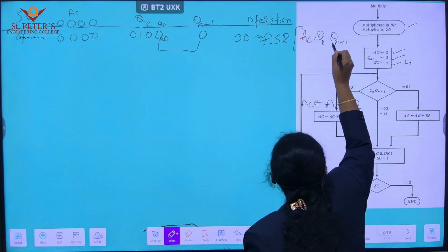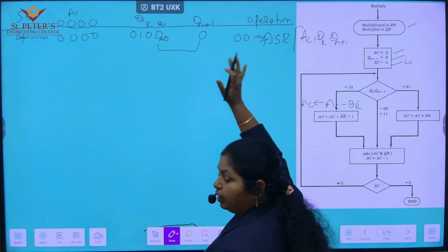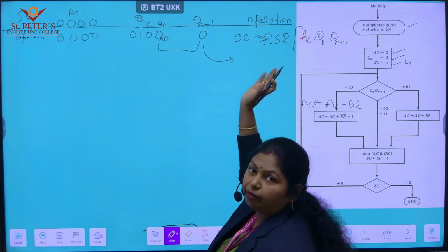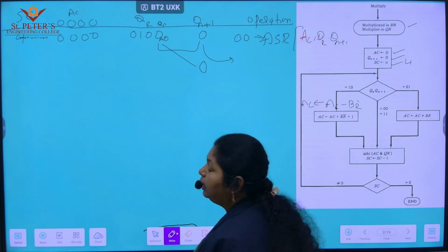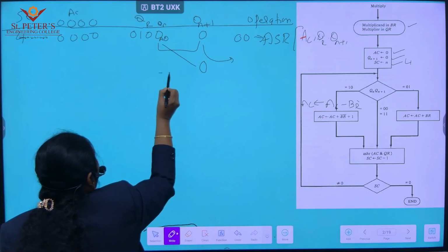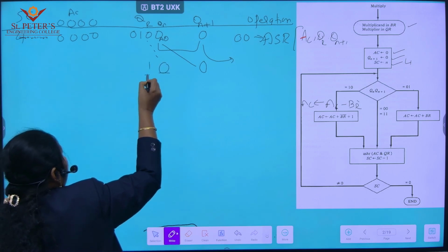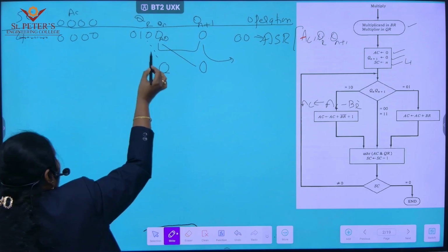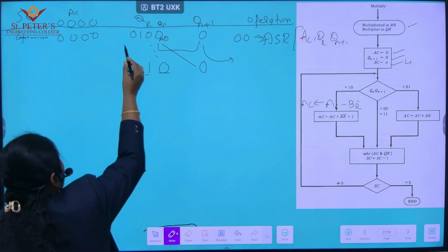We have to perform the right shift operation, which means all the bits have to be shifted right by 1 bit position. A single bit is moved out. Qn will occupy the Qn plus 1 place. Q0 will be occupied by Q1, Q1 by Q2, and Q2 by Q3.